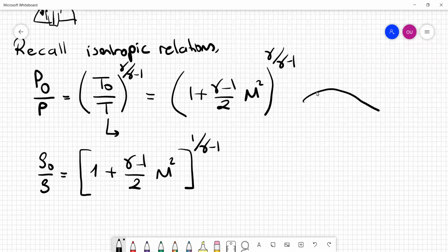So this means that, again, if we are talking about a streamline in an adiabatic inviscid flow, at any point on the streamline, given the flight Mach number or the Mach number at this point, that's actually all you need. I'm sorry, of course, gamma, I'm assuming gamma is given. These are all the parameters you need to calculate these ratios: P0 over P at that location, rho 0 over rho at that location, and obviously T0 over T at that location.